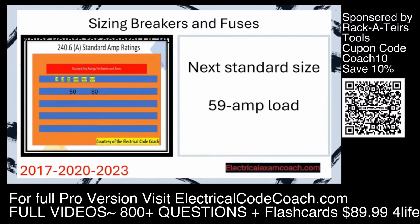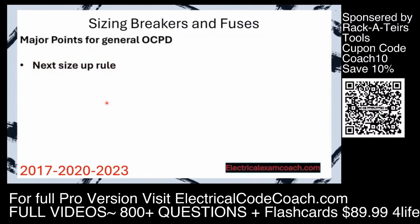So we go 15, 20, 30, and then we look here and we see 50. And then in between 50, there's no 55, and it jumps to 60. If we have a 59 amp load, we're going to choose a 60 amp overcurrent protective device. Now that may not feel good at first when you first start wiring and learning this stuff, but later we'll understand that there are rules in place when we get to sizing our wire that are going to make it so everything's okay and we're totally protected.